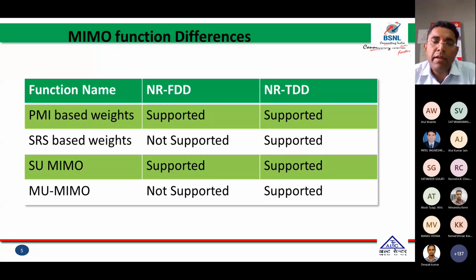Why did they implement time division duplex mode? We will discuss it for massive MIMO, and there is one other case as well, because in our 2G era they only supported FDD transmission mode. Why? Because our voice traffic is 50% of the time in uplink and 50% of the time in downlink. That means 50% of the time we are listening and 50% of the time we are speaking. That's why the traffic is balanced between uplink and downlink in the case of voice traffic.